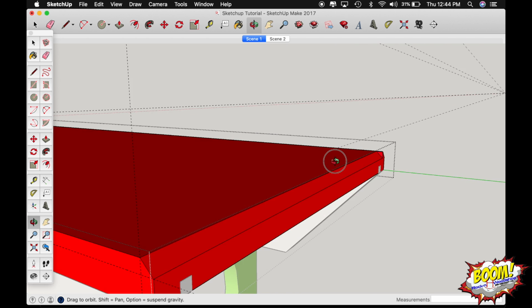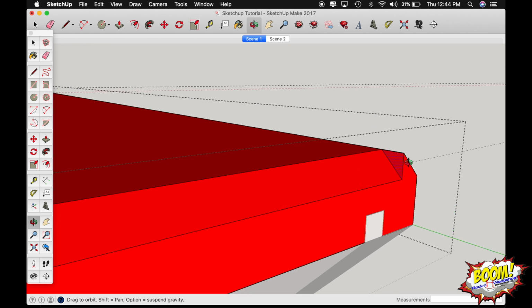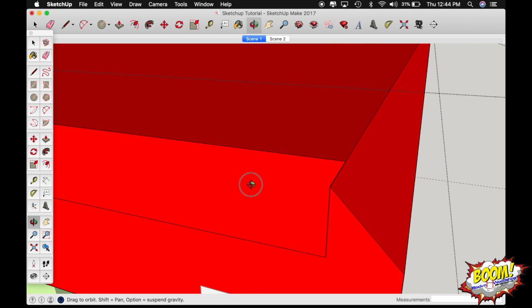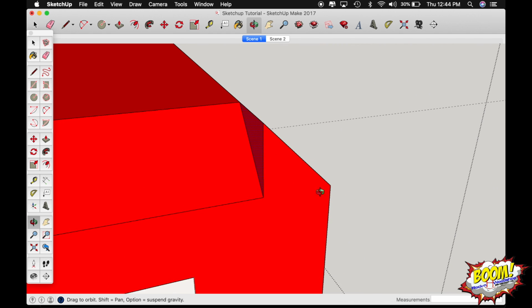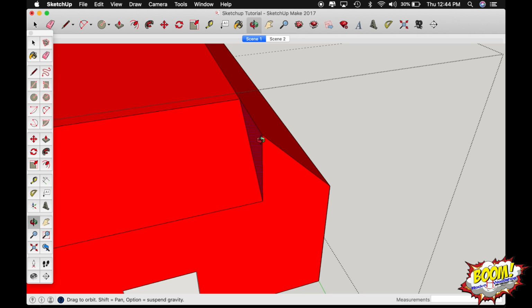Now, after I've dropped it, there is a residual amount that it bottomed out because I've made this 45-degree turn, and I can't drag it all the way across. It has no more right angle dragging to move. So the easiest way to make this corner meet up with that corner is just move it. You turn your move function on, and then just find that point, and it will snap into place. Click it, and then drag it over to that point, and then drop.